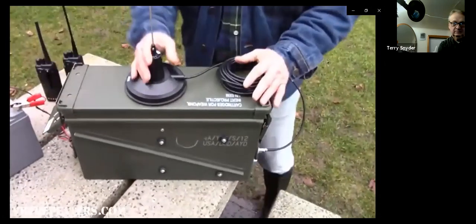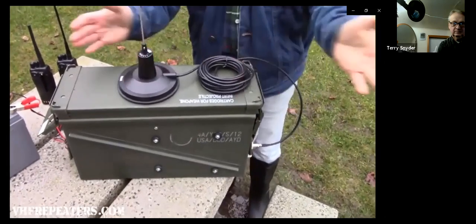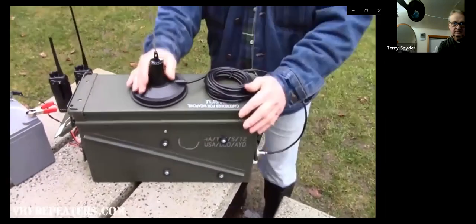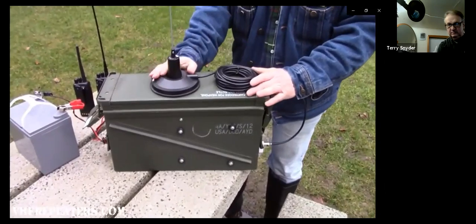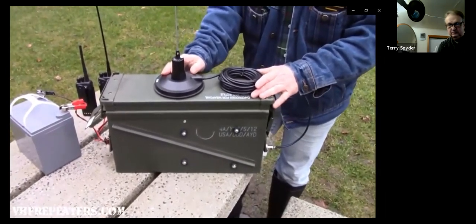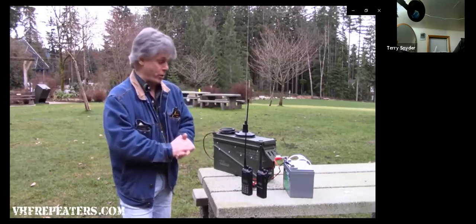This antenna is a Larsen WB150, which will give you plenty of range no matter where you go. Pop this on top of a mountaintop, and you're going to have 30, maybe even 50 miles of range off this one single antenna. The antenna itself is rated up to 150 watts. With minimal battery draw of less than 1/10 of an amp, and only 3 amps on high power transmit, this unit will last you all day on a fully charged battery. Full power output of 25 watts with direct line of sight will get you lots and lots of distance. Fully compatible with all makes and models of analog two-way radios, including Kenwood, ICOM, Yaesu, Motorola.